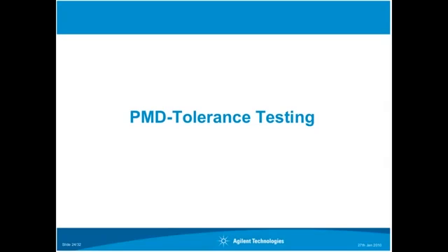And I got some quotes from people saying, okay, we have our receiver, we have maybe 5 customers, and all 5 customers want different characterizing methods. So it seems that this is really a pain. And at that point, we are still talking just about the very basic characterization for first order and second order PMD. And since the receivers are now getting more intelligent, and they have some adaptation algorithms, not only the receiver threshold, but also some sort of filters which need to be adapted, you are going to see that the receivers will have some dynamic properties.